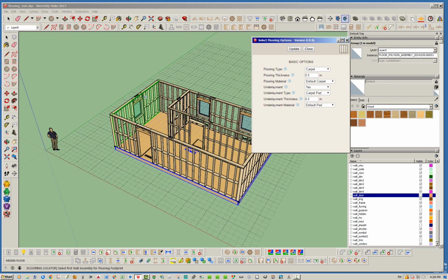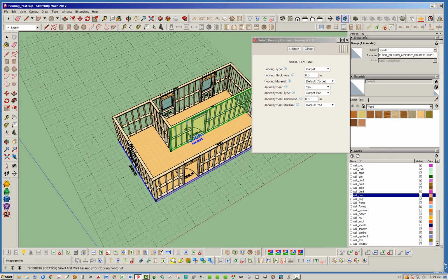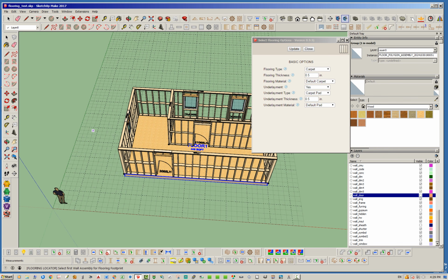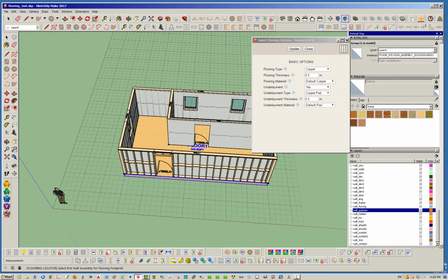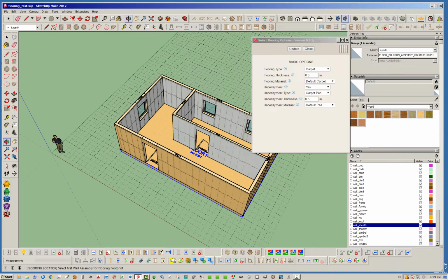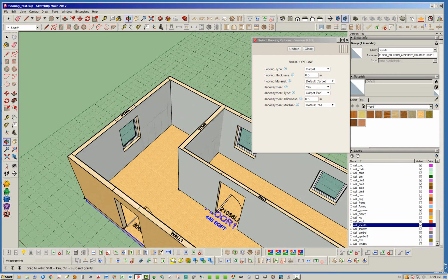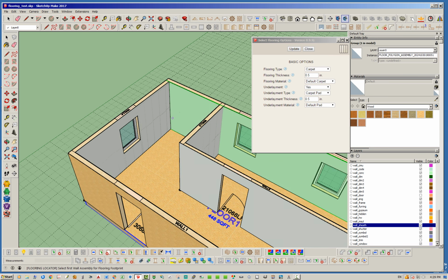Now you see as you mouse over each wall, you are highlighting the face of the wall. To make this a little easier, let's turn on the gypsum and the cladding, or the sheathing at least, just so we can see those wall surfaces easier. It helps make it easier to select the wall because you're not mousing through the studs, you're mousing on the surface. It will highlight green, and that allows you to select that wall. So we'll go ahead and select it.